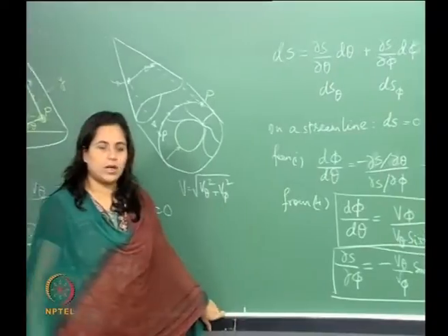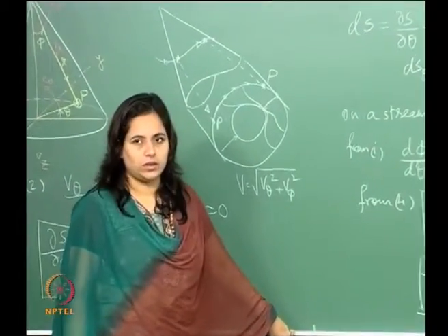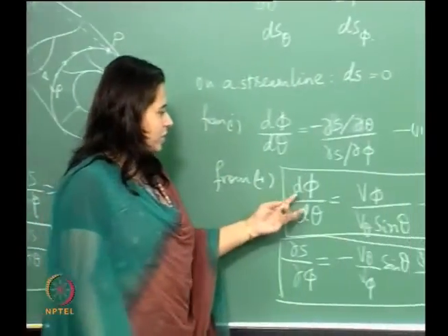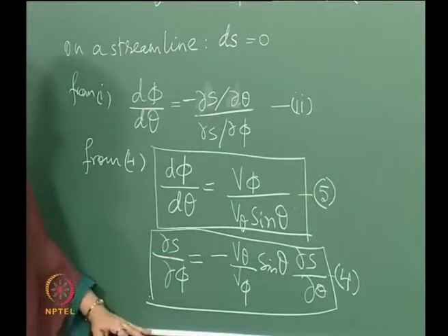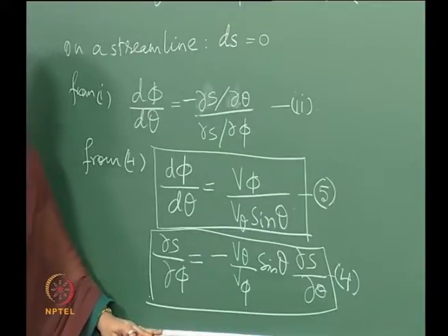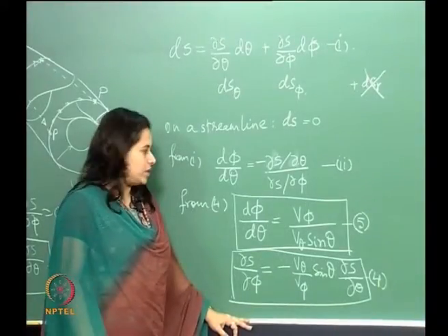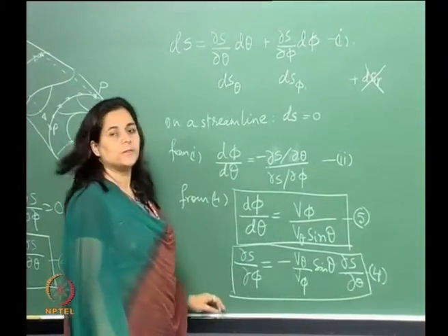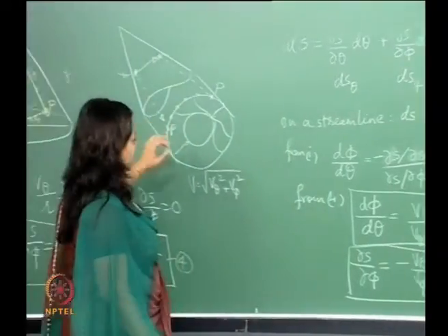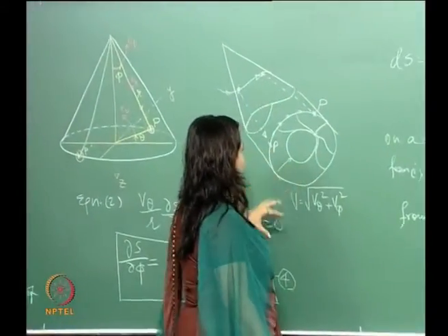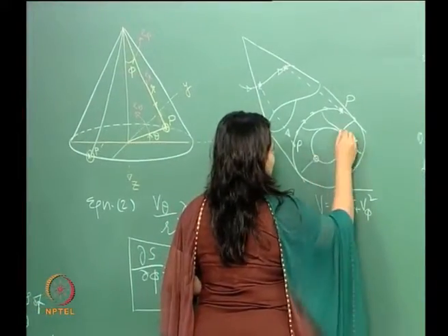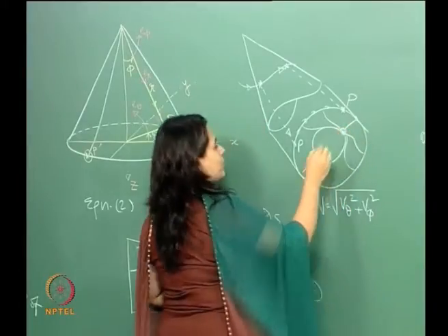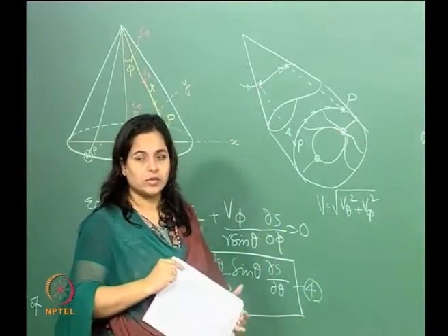The question to ask here is, which is always fine: this gives us a shape in terms of these velocities, and this gives us a change in entropy in terms of these velocities. So, numerically there should be no problem. Is there any issue here? The hint is that in this space we had a stagnation point, if you remember. These are the two stagnation points, and this was also a point of vortical singularity.